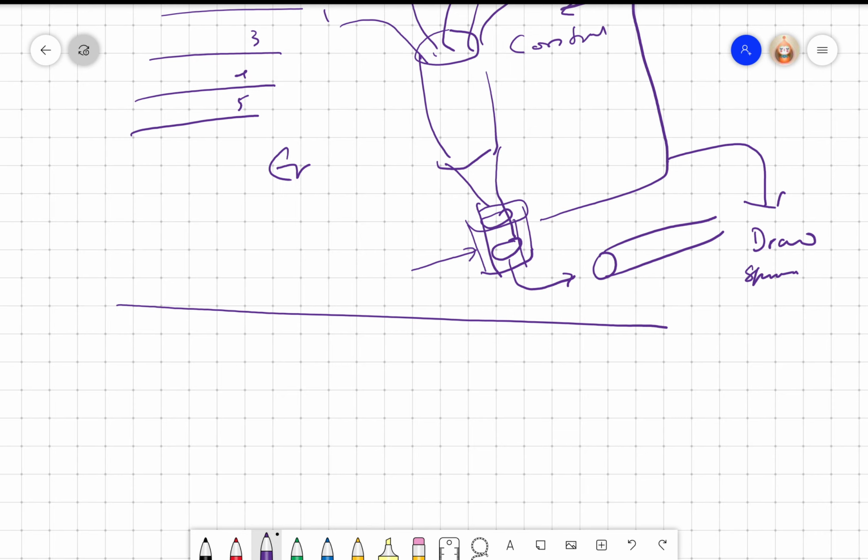Then we also saw this epsilon naught, epsilon r, A by d, C. We see epsilon r dependent capacitive sensors. As I said, they are used in the textile industry, they are used in the paper industry, wherever you can look at epsilon r.